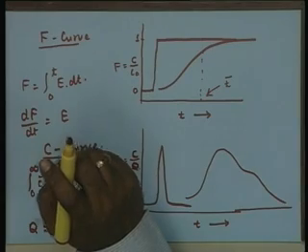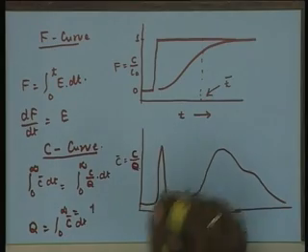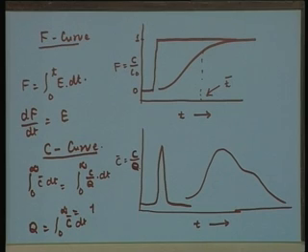Quantity in what, sir? Here you are not putting it in continuously, you are putting it in only one shot. Say for example, you put 1 gram of some inert dye into the reactor initially, and after that you monitor its output response. Now this 1 gram, theoretically, if it is an ideal plug flow, should come out in a short period of time, in as much time as it has been fed in, but it will not emerge in one go, it will come out in small lots.